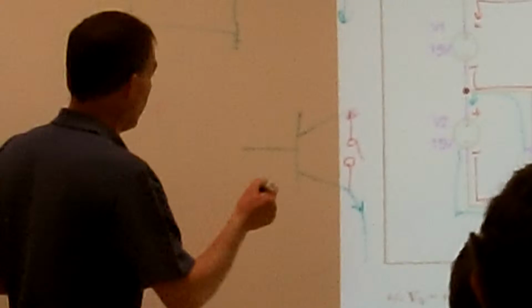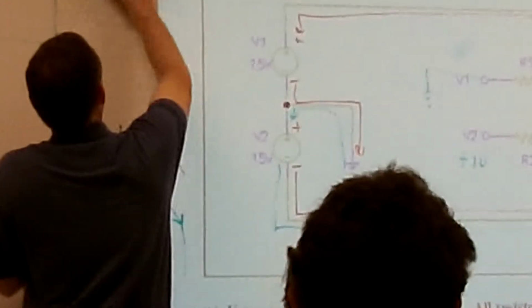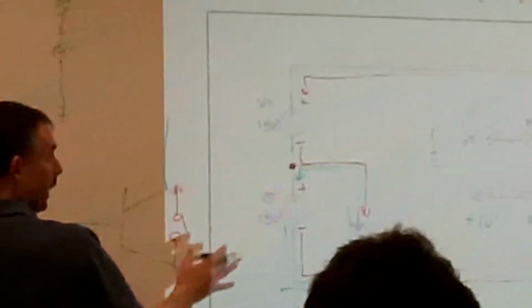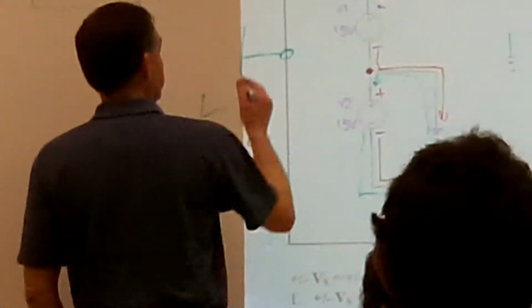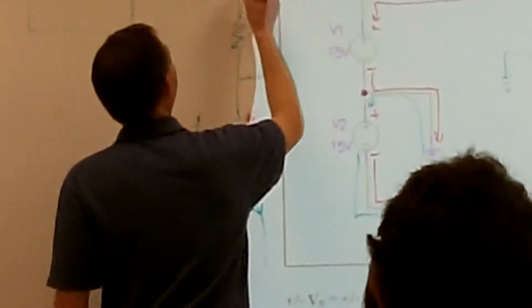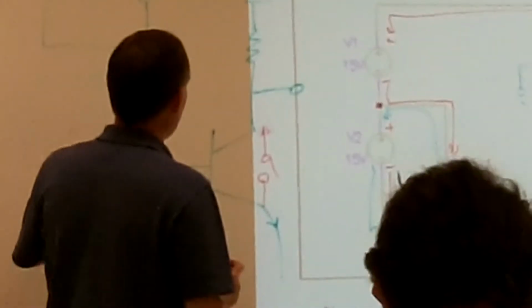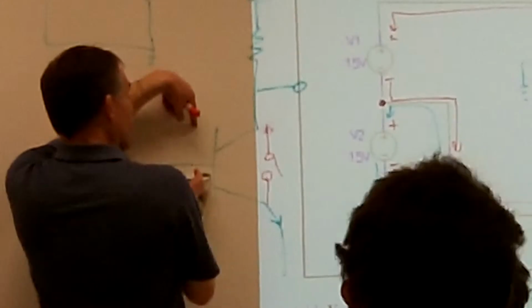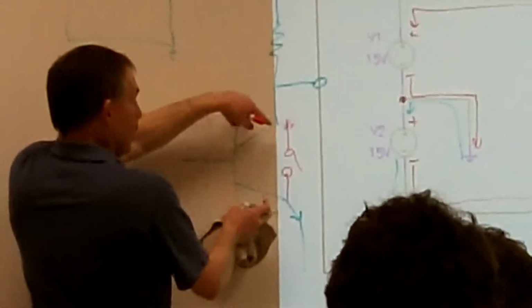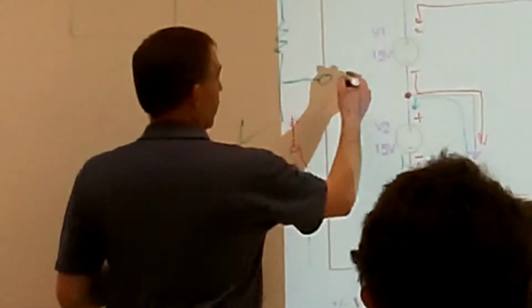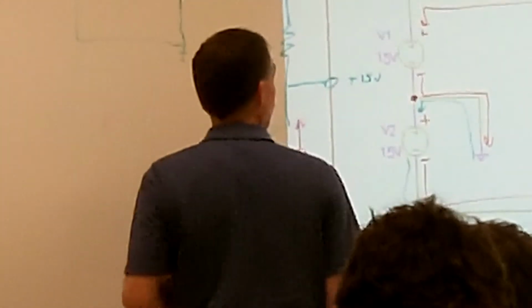And that's kind of one of our benefits of having an op amp, because we can swing it both ways. So for example, on the transistor, if I had plus 15 volts, if my transistor was turned off, I'm going to be measuring across my open and I would get plus 15 volts.